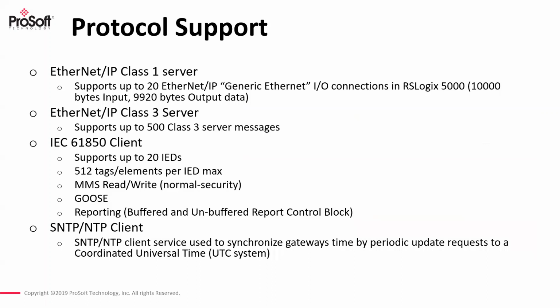So again, as we just looked at the protocol support, the module itself operates as an EtherNet/IP class 1 server and can support up to 20 IEDs with up to 10,000 bytes of input data. These are just the general specifics on the module.